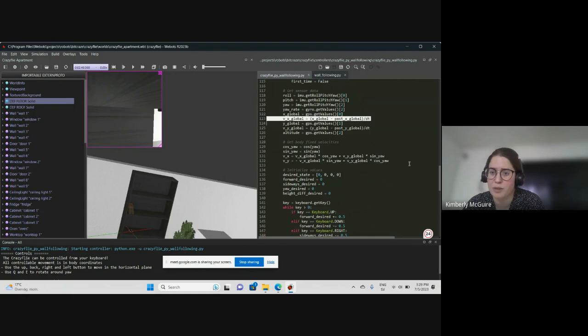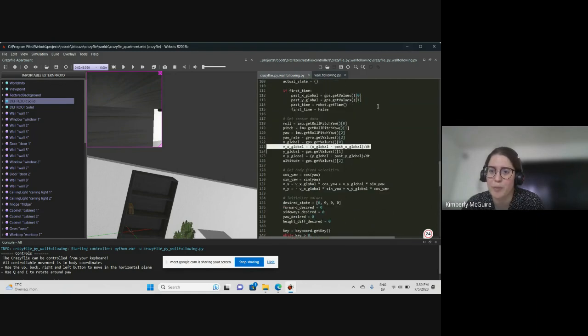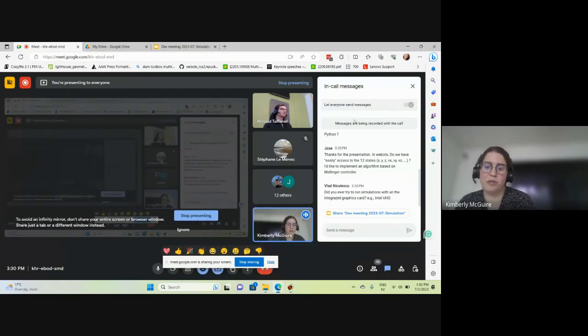And of course, body fixed velocity. Roll, pitch, and yaw is fine, because you can get that directly from the IMU, and you can also get roll, pitch, and yaw rates from the gyro. So that gives you the full state, but you would need to hack around a bit for the full states. It would be weird.